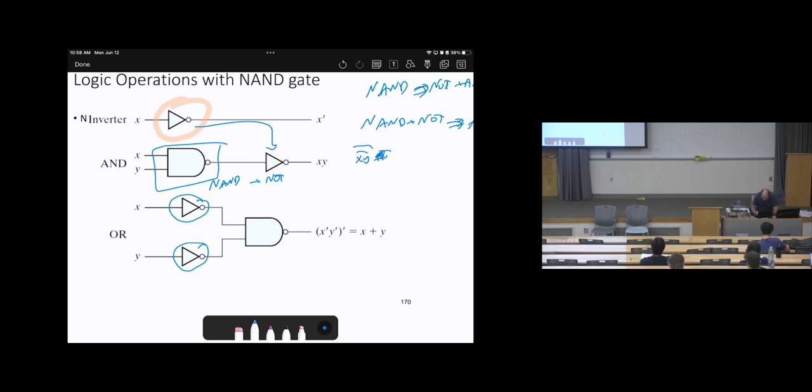Let me make sure, we will find the complement for it. Okay, let me erase this. Here in NAND, in order to create OR, we will put bars above the inputs. So here is X bar, Y bar, then (X bar Y bar) bar. Therefore, according to De Morgan's, it will be X plus Y. That's how we get it.